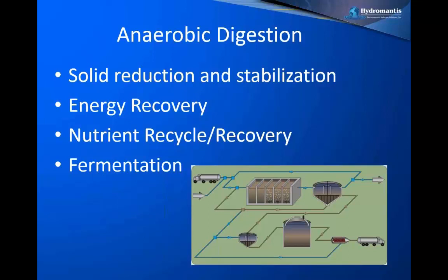In recent years, there has been a lot of emphasis on energy recovery as well, and anaerobic digestion is gaining more and more importance with respect to energy recovery options. Also, since there are a lot of new regulations with respect to discharge of nutrients in the effluent, the side streams from the solids processing facilities, which are rich in nutrients like nitrogen and phosphorus, the recycling of those nutrients back to the liquid train is also an important consideration.